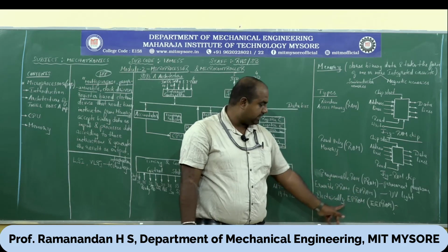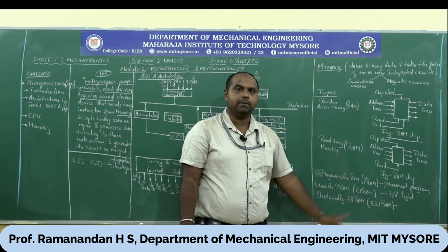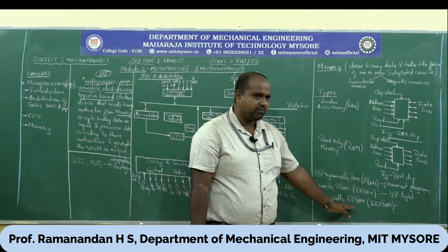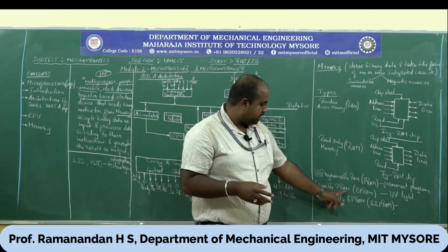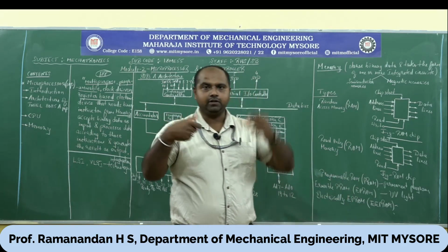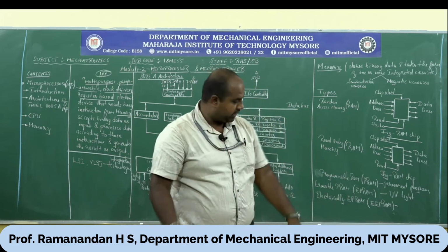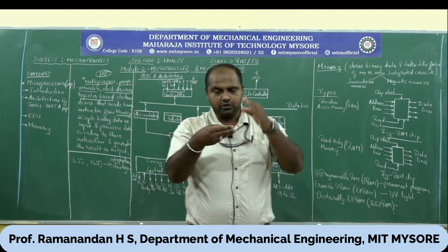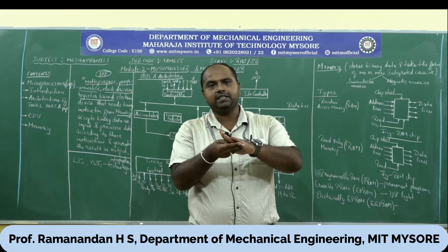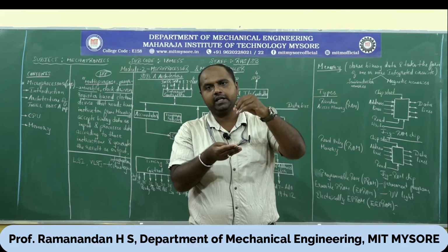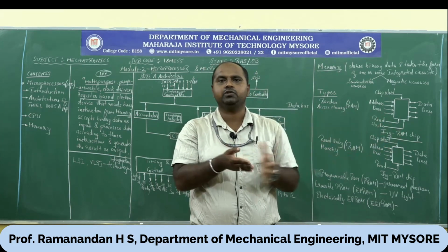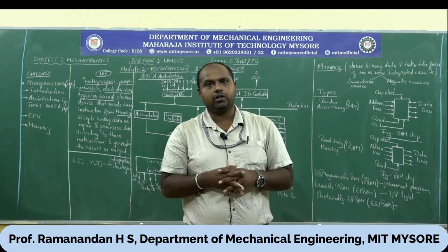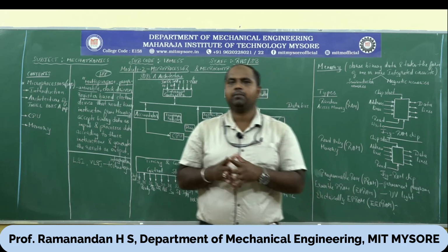The last one is EEPROM, or E-squared PROM, electrically erasable programmable read-only memory. For the above one, the EPROM, you have to remove the unit and expose it to UV light. But here, in the EEPROM, you need not remove the unit. The unit stays where it is. You can just erase the data and feed a new set of data to the EEPROM. That is the advanced read-only memory that exists in a microprocessor.